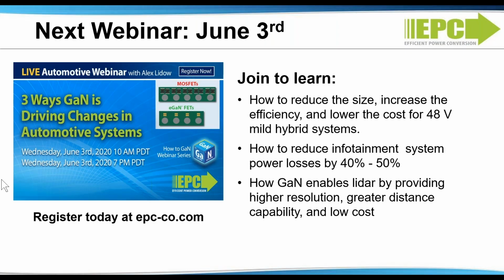Okay. We have a question about the devices. eGaN FETs do not have an integrated diode, is that correct? So eGaN FETs, unlike MOSFETs, have no PN junction body diode, but eGaN FETs will conduct in the reverse direction. What happens is it's just the channel that turns on.